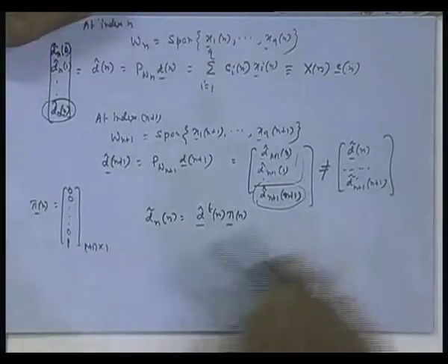Okay, that is the entire approach. And you understand this journey will take us to the optimal ones: C vector n, then C vector n plus 1, then C vector n plus 2. As more and more data are used in computing epsilon n square, it will be a better and better estimate of the original epsilon square, and therefore this coefficient sequence will march to finally the optimal ones. Exactly, not in mean, unlike LMS. And no searching business, it will march very fast. So this is what it is.